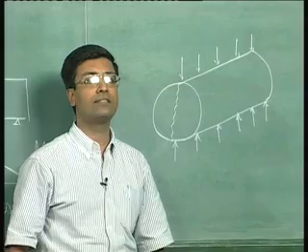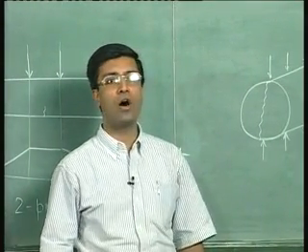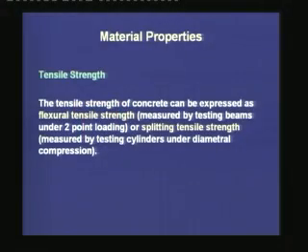Now, both these tests are covered in detail in the concrete technology course. Hopefully, you should be aware of both these tests. These two tests, the flexural tensile strength and the splitting tensile strength tests, are easy to perform. There is a third type of test for calculating the tensile strength of concrete, that is the direct tensile strength tests. These tests are more difficult to perform, but still they are done for research purposes.